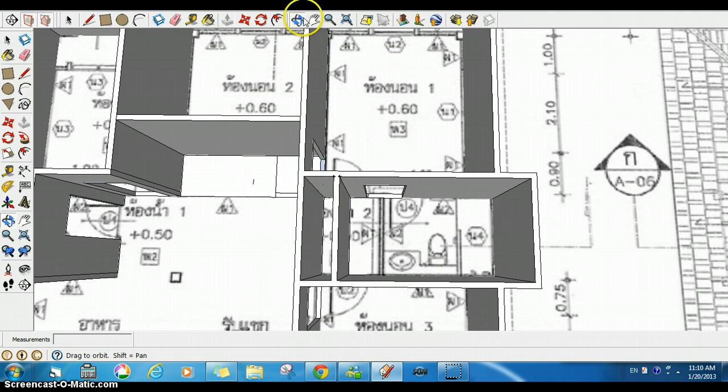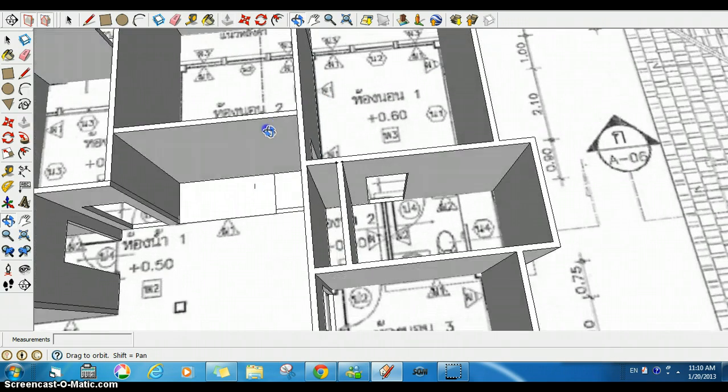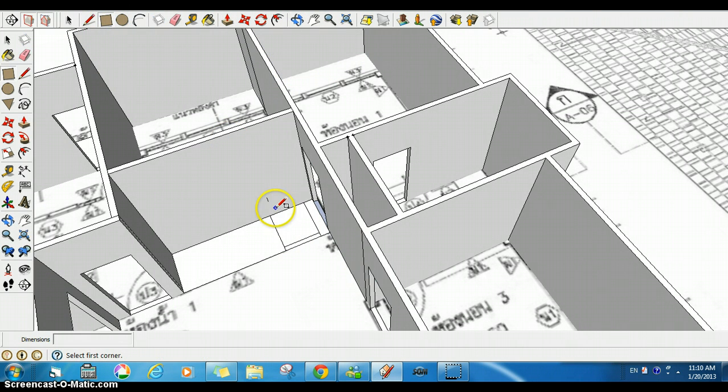I told you before why I don't like pushing doors in and out by themselves, and I will show you right now why. Okay, we're gonna put a door over here, and we're gonna make it 0.8, 2 meters, enter. Okay, that's not good. Oh, you see what happened? I pressed the wrong value, and it made that huge. So go Alt, backspace, and we'll try it one more time.